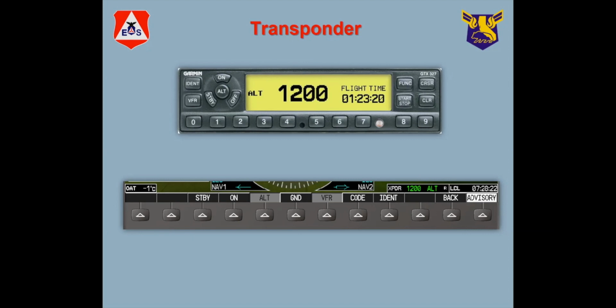And basically, it's a 4-digit code. At one time, it was 3. And what it does is when the radar sends out a pulse, it looks for a return. And that return that you have, the address of that return might be 1946. That's what air traffic control assigns you as a number for your transponder. It's called squawking your transponder code.